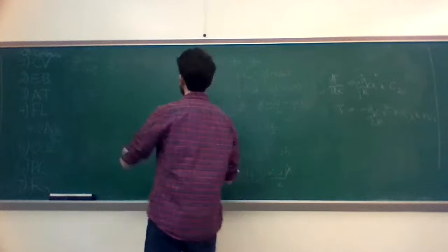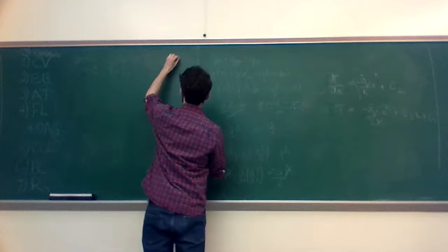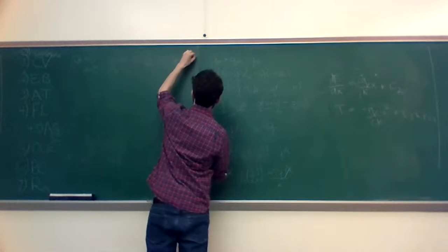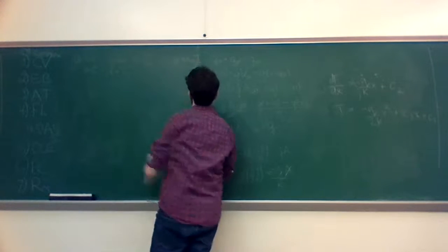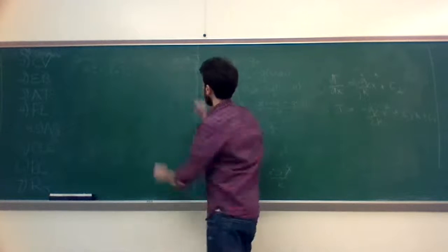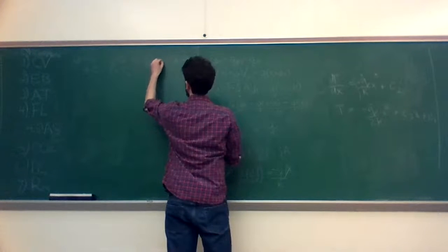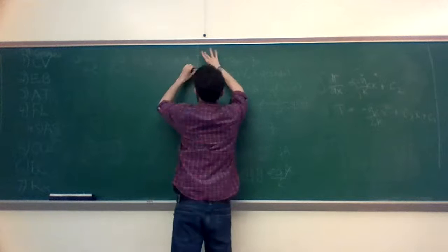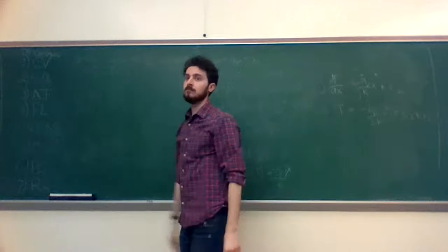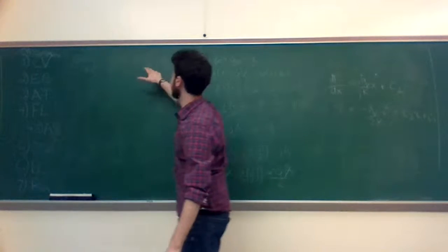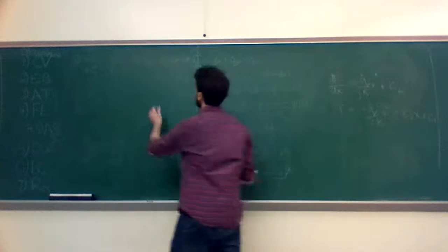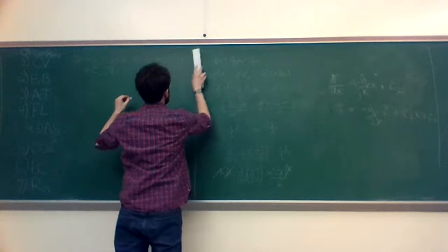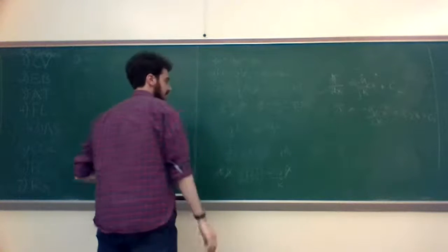So q, remember, q equals negative kA dT/dx. Now if that's 0, then k and A are not 0. So basically it means that dT/dx has to equal 0. So no slope. So if q is 0, if it's insulated, then dT/dx is also equal to 0. Okay, dT/dx is 0. I think that's the easiest one to do first.